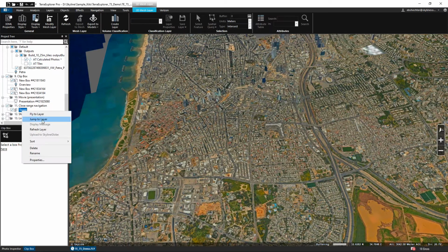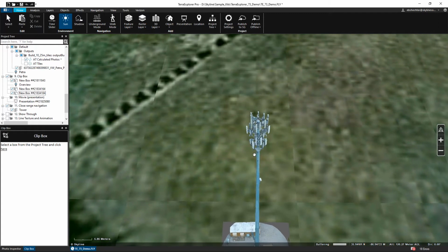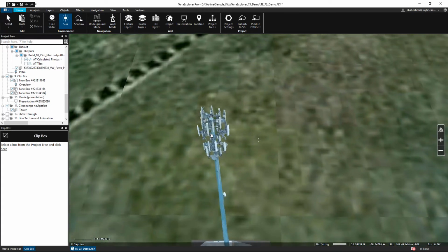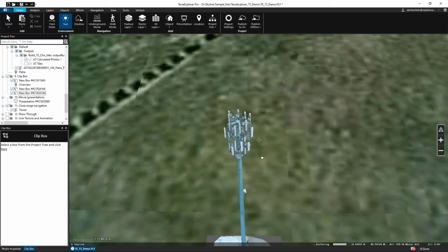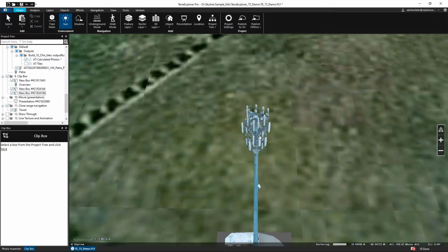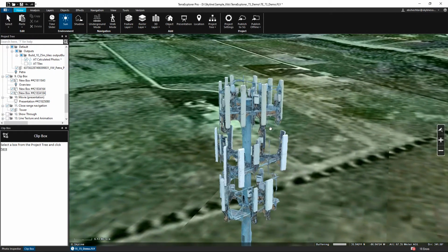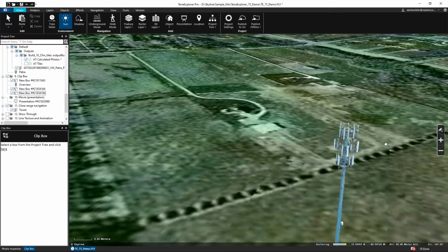One of the things that the zoom to cursor is used for, and this is a nice demonstration of it, is let's say the cursor is over here and you want to zoom on the building or on the section, it still zooms in, as opposed to zooming to where, so you don't have to have the center sign hit the object exactly. And it also knows, even if you're missing a little bit, let's say if I'm zooming over here, even though I'm seeing through it, it still detects that there's an object here and it zooms nice and slow, as opposed to over here, see, when there's zooming to the background.